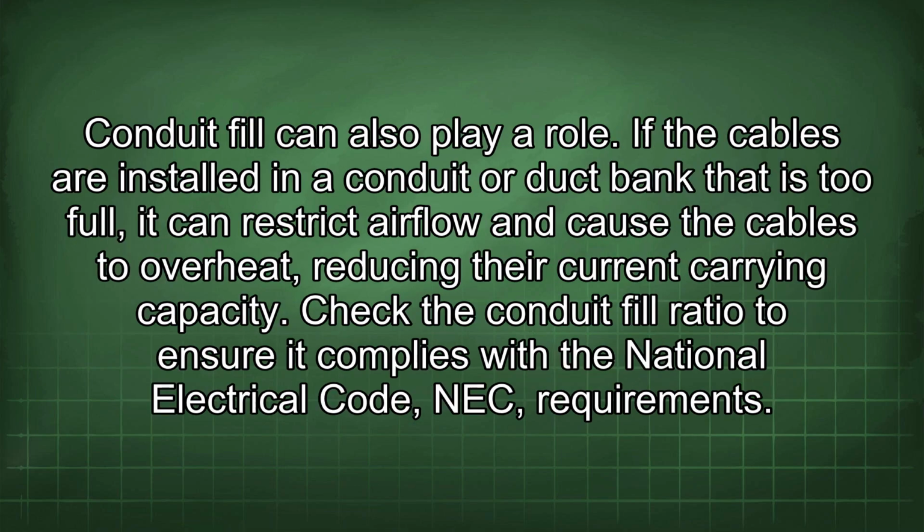Conduit fill can also play a role. If the cables are installed in a conduit or duct bank that is too full, it can restrict airflow and cause the cables to overheat, reducing their current carrying capacity. Check the conduit fill ratio to ensure it complies with the National Electrical Code (NEC) requirements.